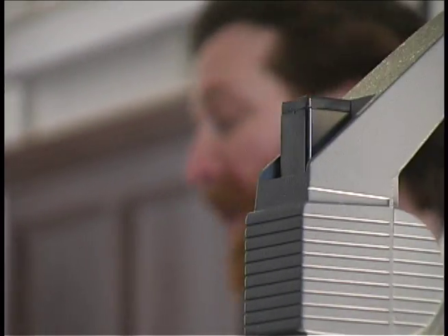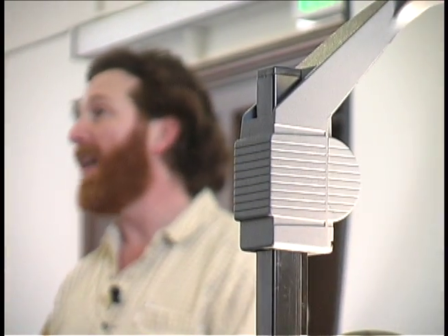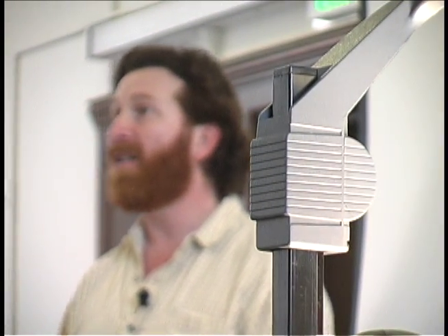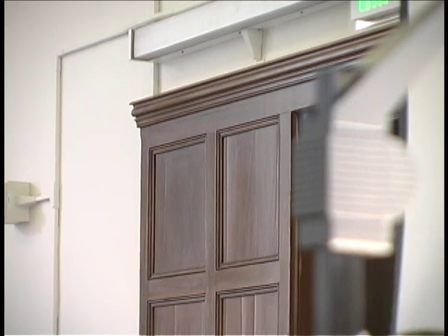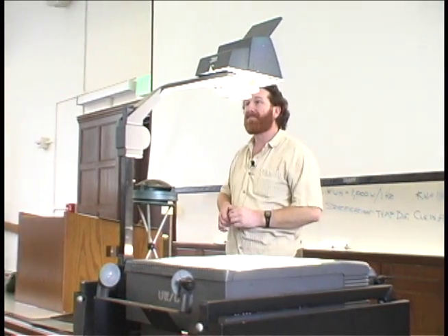The important thing to know about flux density is, let's see, 9 to 3 are the hours of collection that you're most concerned with. Anything before 9 o'clock in the morning or after 3 o'clock in the afternoon, the sunlight is going through a lot of atmosphere, and most of the usable energy is being reflected and refracted and absorbed, and it's not doing you very much good. So if you're shaded before 9 o'clock in the morning or after 3 o'clock in the afternoon, don't worry about it, because it's not going to hurt you that much.